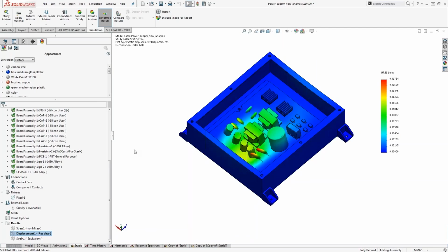Right? But what if I wanted to know how the stresses were being developed as it was starting to load and then until the final load point? Unfortunately, we can't really do that with the linear static analysis. It assumes that the load is being applied slowly and gradually, and the results that we're seeing here are the stresses and displacements at the end of that load. Right? So it doesn't give us any information in between. So that's how we can approach it with the linear static analysis.